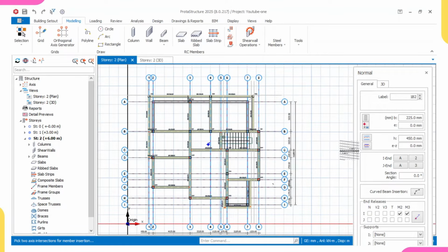But if it fails in the course of our design, we will not increase it. To save cost, we will be using the minimum. If the beam fails, we increase the beam depth. If the column fails, we will not increase the size of the column. So don't forget, our aim is to save cost, while safety is still our priority.